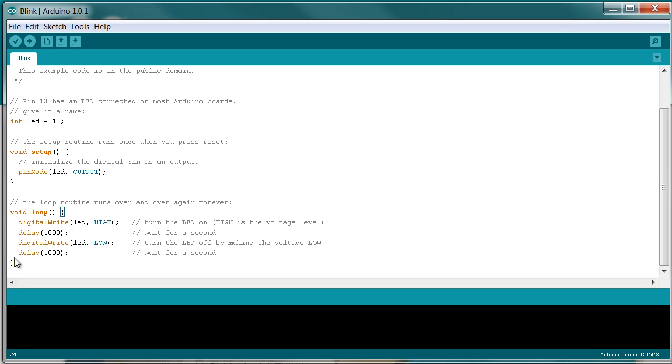And then we're gonna do the same as before. We do a delay of 1000, meaning 1 second, and we keep looping and looping these instructions over and over and over. So we turn on the LED, we do a delay of 1 second, then we turn it off, delay 1 second, then we jump to the beginning, and the code keeps doing this over and over and over.